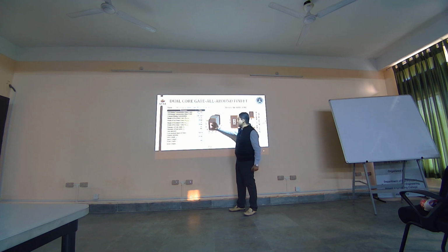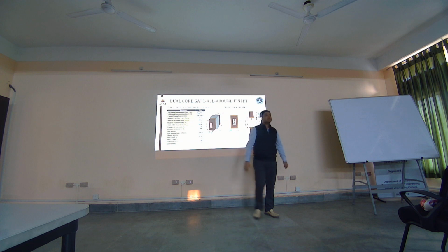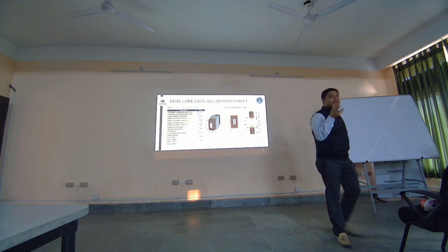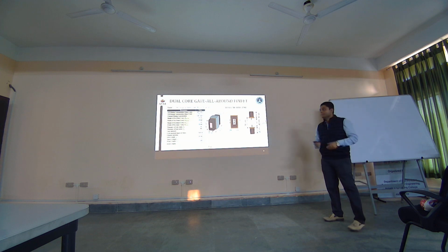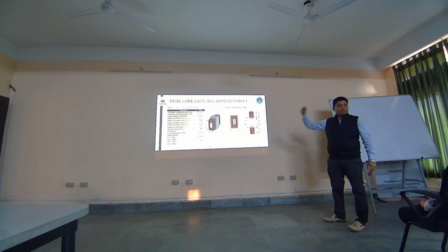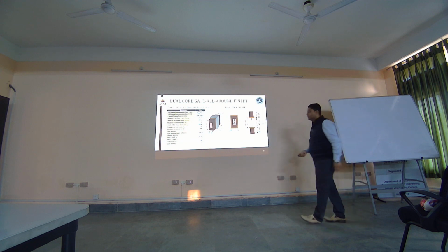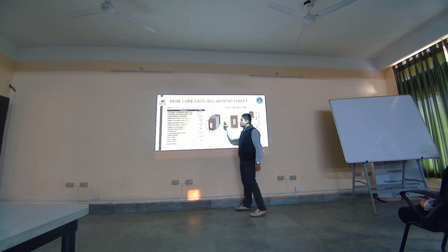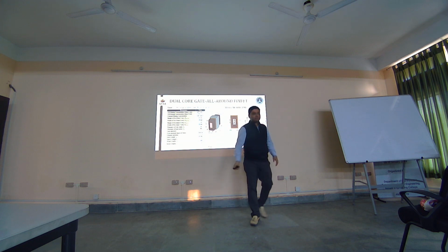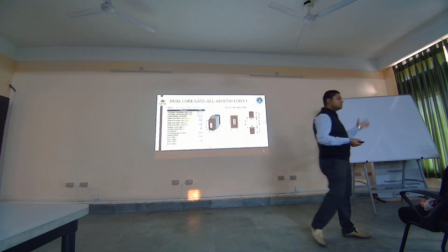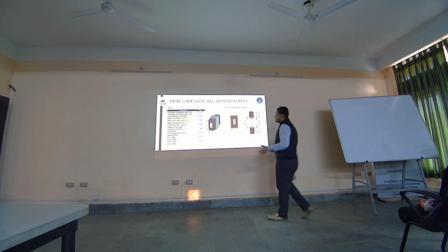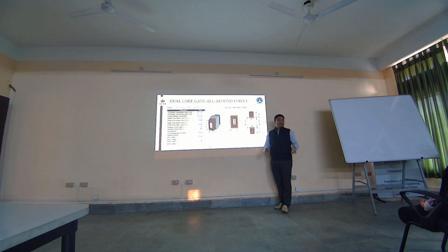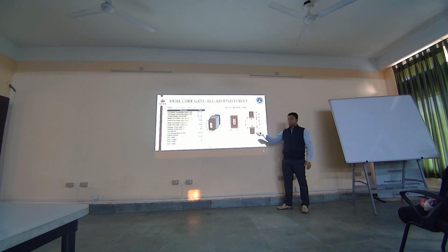The second point is that by changing the doping concentration on the inner core and outer core, we were able to see the change in the electric field profile and the effect of the gate work function and all this stuff. So more than a device directly aimed at application, this was designed to study the properties of the ribbon FET. The ultimate objective was not to directly use it in circuits. As gate all around FETs were announced by Intel and Samsung simultaneously, we wanted to see how these devices would perform if they were modified.